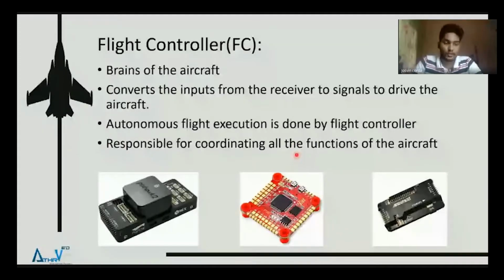This Pixhawk Cube, the flight controller on the left, is mainly used for professional grade applications, like big multi rotors, like in case of pesticides or aerial mapping. The one in the center is mainly for hobby grade, that is for FPV racing drones, freestyle drones, all those things. These are comparatively small and are made to save on weight and space. And the third one is the autopilot or APM flight controller. This is usually suggested for entry level or beginner pilots who are interested in joining the hobby. This is fairly inexpensive and you'll get a touch of how an aircraft handles.